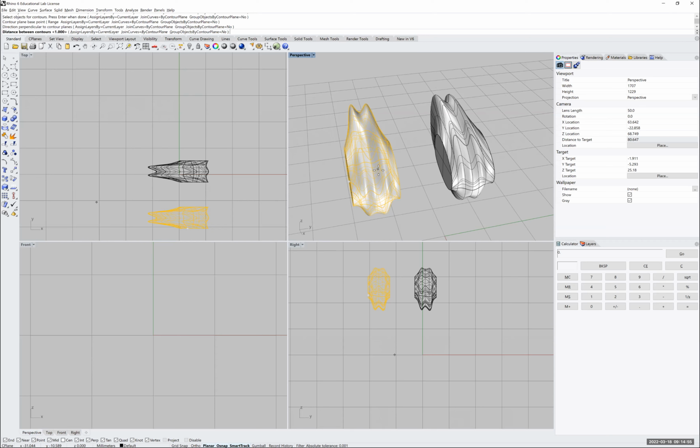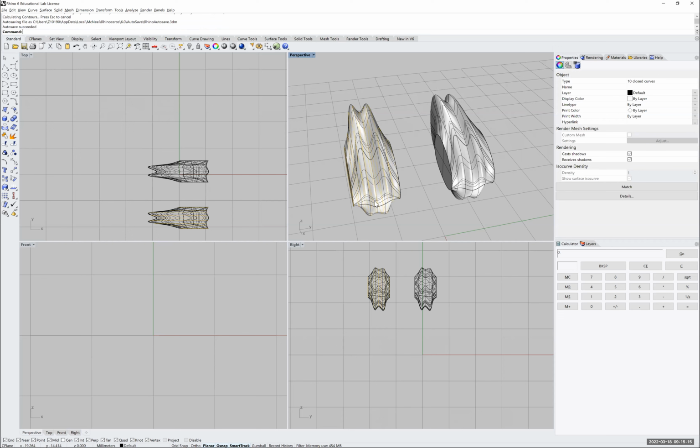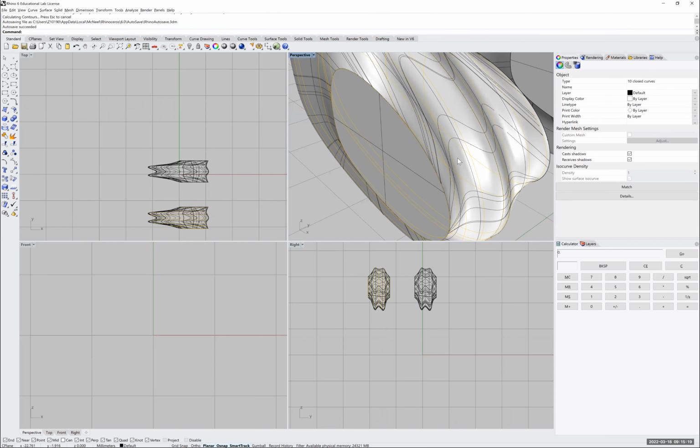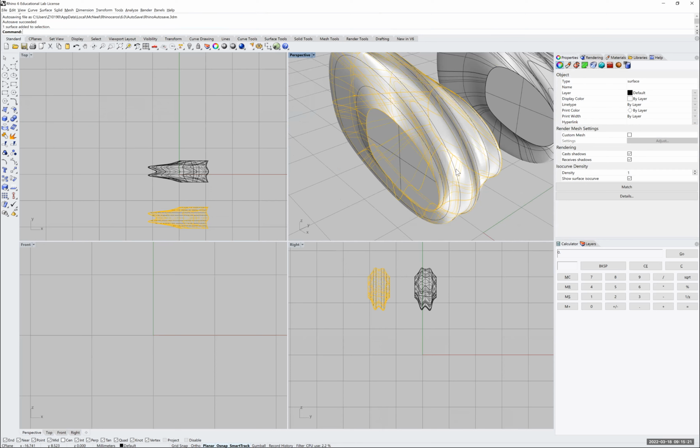Right now, because of the scale we're working with, obviously this is not an object to scale, so I'm going to keep it at 1. So in this case, if my material is 1 millimeter thick, then I'm going to have to define the distance between the contours to be 1. I'm going to click on 1 and hit enter. And now you can notice that I have a new set of curves that are consistent with the shape of my object.